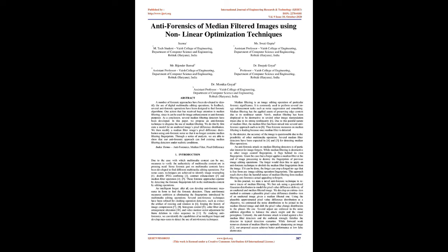It is commonly used to perform several image enhancement tasks such as noise suppression and smoothing. Median filtering has the added benefit of preserving edge content due to its nonlinear nature. Recently, median filtering has been shown to be destructive to several other image manipulation traces due to its strong nonlinearity 6. Due to this nature of the median filter, it has been incorporated into several anti-forensic approaches such as in 8. Thus forensic measures on median filtering are important because once median filtering is detected, the authenticity of the image is questionable due to the possibility of other multimedia operations.